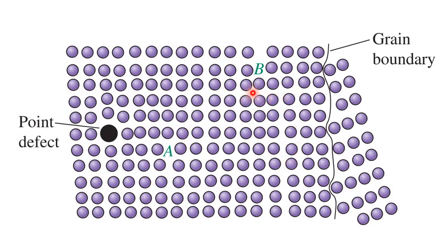If dislocation B was not here, dislocation A would need less stress to pass through this area. Again, because the structure of the material here deviates from the perfect structure, when another dislocation like dislocation A moves toward this area with another dislocation, it needs higher stress to pass through this area.